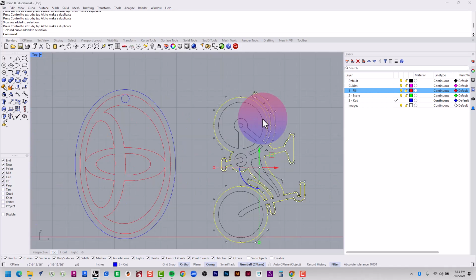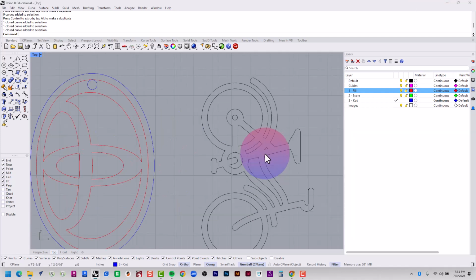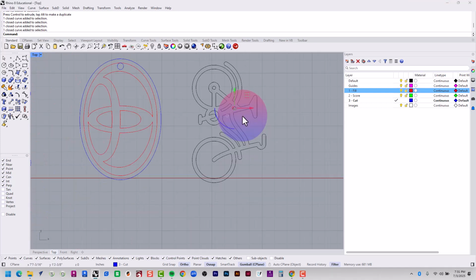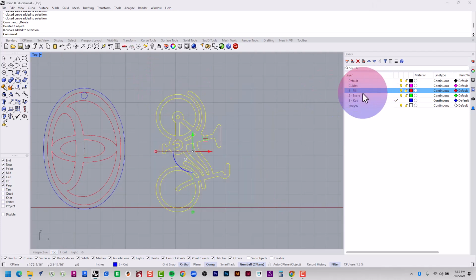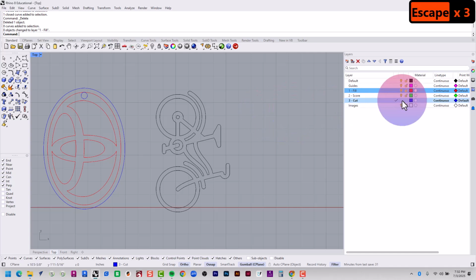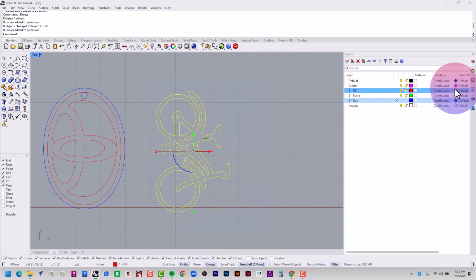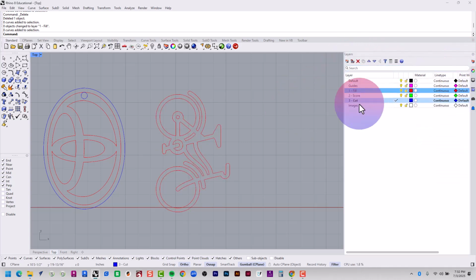So it looks like I got a closed curve, a closed curve, closed curve. Looks like these are a bunch of closed curves. I'm going to delete this little guy just for simplicity since it's so tiny. And the first thing I'll do is select all of that, and let's fill that. Okay, it didn't change red, so I'm going to select all that again, go to Properties, and put by layer. And then now I'm going to go to Layers.